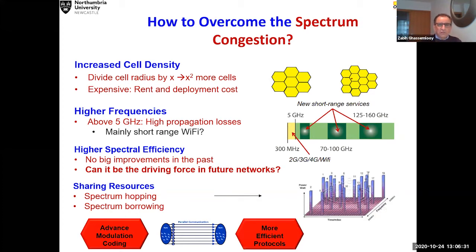So the world of telecommunication, just like anything, is a world of compromise. You add something, you have to give away something else. And then RF has been very good in pushing the frequencies higher and higher, moving up the frequency scale. And of course, that's a very logical way of doing it, because we know by definition that roughly between 10 to 15% of your carrier frequency is your bandwidth. So it's inevitable that you have to push to higher carrier frequency, which will push you into the millimeter wave range. And then beyond that, you can see what we are going to see.